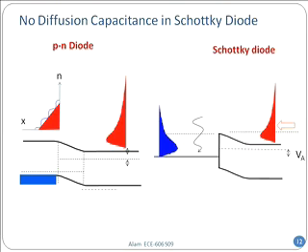So this is about Schottky diode, and this is, I want to emphasize, very different from the PN junction diode, where you can see the red triangle on the left hand side is the minority carrier. Unless you have a lot of traps sitting there, then it stays on the minority carrier side for a long time. As you bounce your potential up and down, then the blue wavy line says how it diffuses. Each individual electron needs to go, and that takes a lot of time. So therefore, it's actually a slower device.